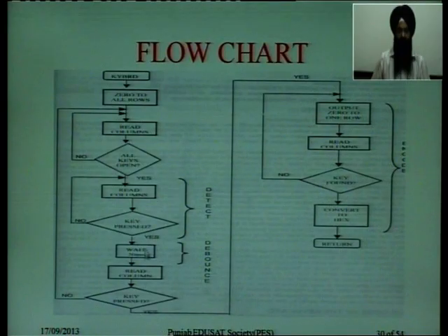If yes, then wait 20 milliseconds. This wait is to ensure that the key is actually pressed and that there is no noise signal or any distortion. After 20 milliseconds, we again read column. If the key is again pressed, then we process further. Otherwise, if it was a noise or a wrong signal, then we will get no key pressed and we will go again to read columns.